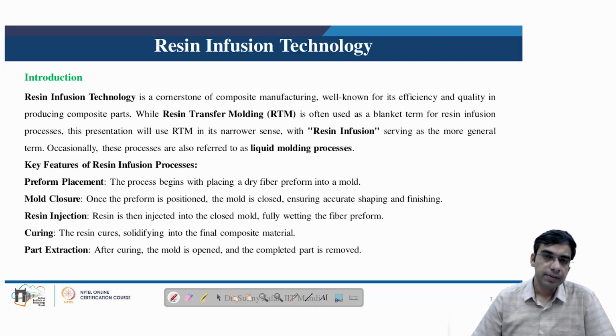These processes are popular when we are using resins or thermosets as the matrix. Especially these types of matrix are very well compatible with high performance fibers like glass fibers and carbon fibers. Because of this, the combination of these materials, that is the epoxy based resins, glass and carbon fibers, are popular in making wind turbine blades, which need to be light in weight despite their large size.